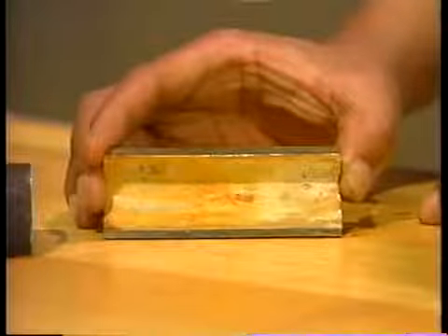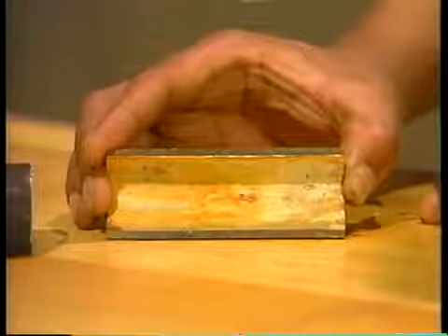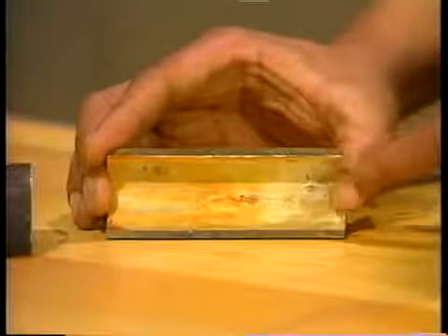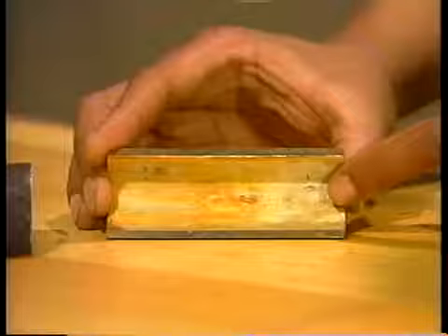Now, one way this can happen is when deposits from boiler water coat the inside of a tube. Scale is an example of a deposit from boiler water. When scale gets too thick inside the tube, it insulates the tube from the cooling flow of water or steam. The metal will overheat, weaken, and then rupture. Blockage in a tube can cause inadequate flow of water or steam through the tube. If the flow is so restricted that the tube can't be kept cool, tube failure from overheating will eventually result.